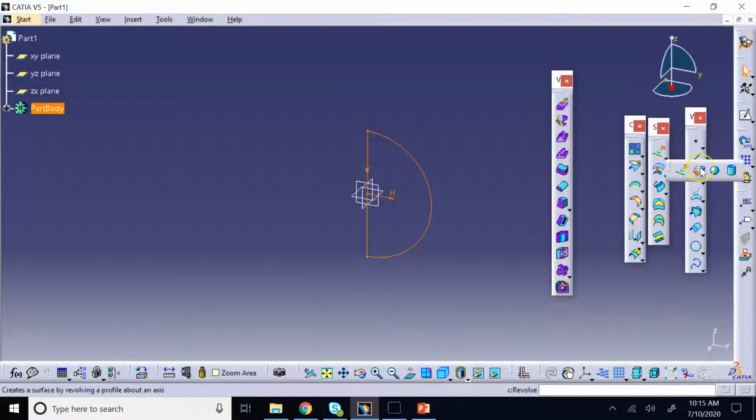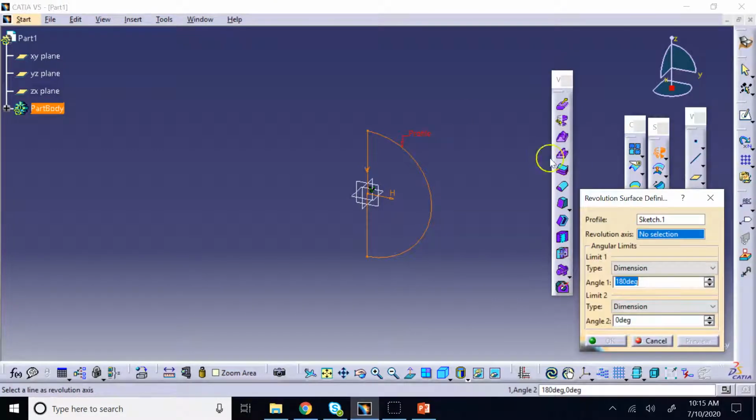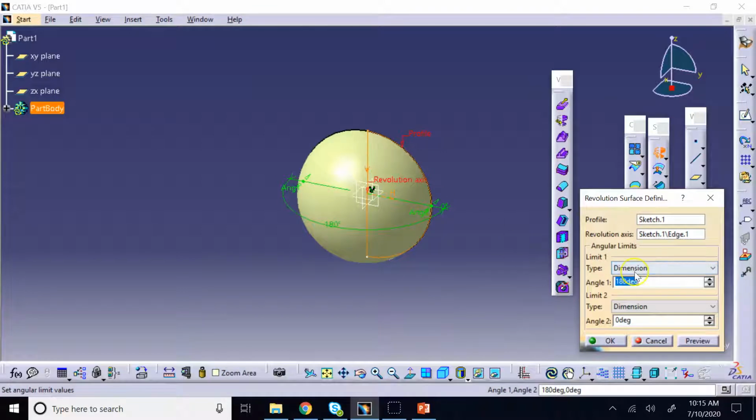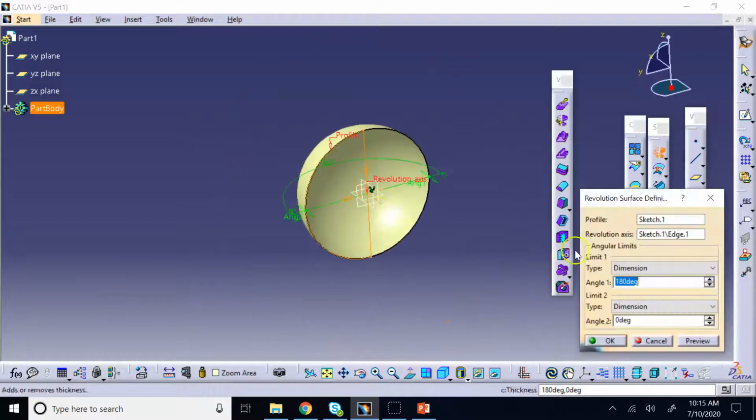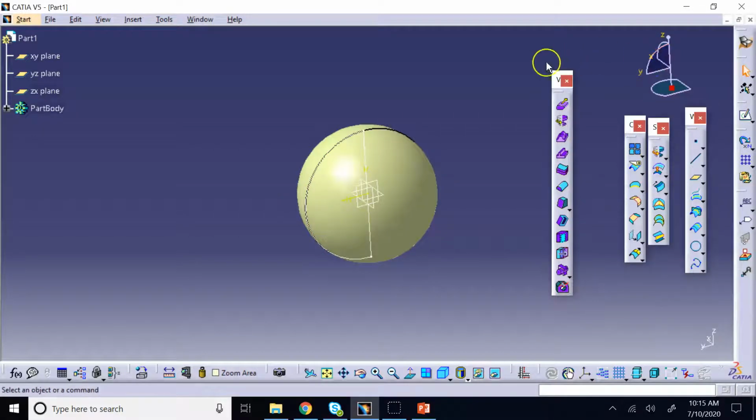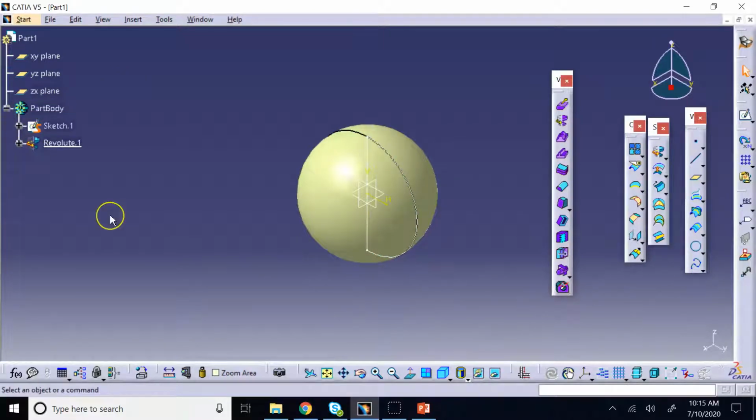So if you expand extrude, then you also have the revolve command. By the way, you can directly create a sphere or cylinder if you want to, but just for the moment I use this guy. For axis of revolution I use this. Then I can provide the amount of rotation I want. Do I want full revolution? Do I want 180 or so on and so forth? Right, so I can provide the angle, and there we go, right? So I could get myself a spherical surface, and then if you want, I can show you later how to convert that into a solid part.